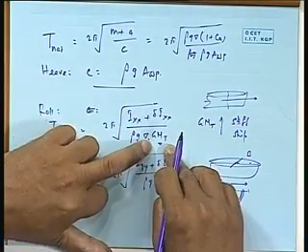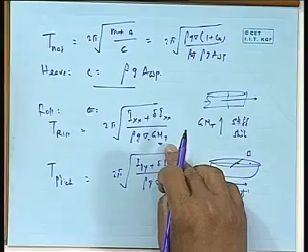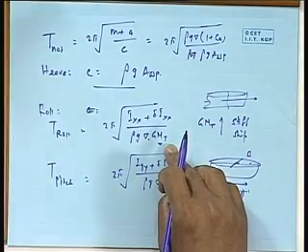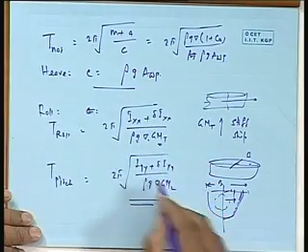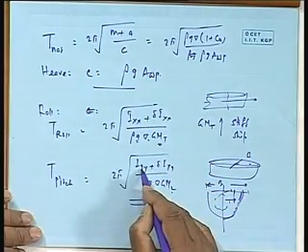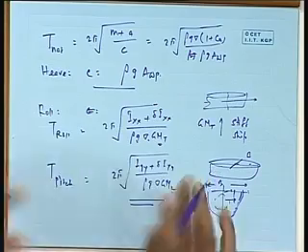You know the GMT value. Our requirement is only 0.15 meter, but most ships have 1 meter or so. So you can find out T roll, and you will find that it comes out to be around 10 seconds. Similarly, you can find this also. This also becomes of similar order, because GML is high, but I_yy is also equally high, so they cancel in the same order.